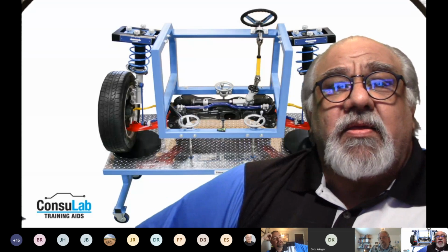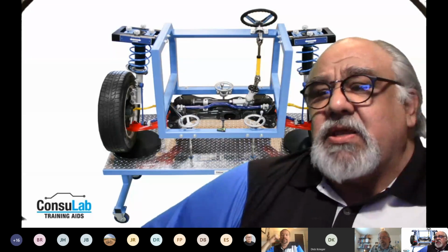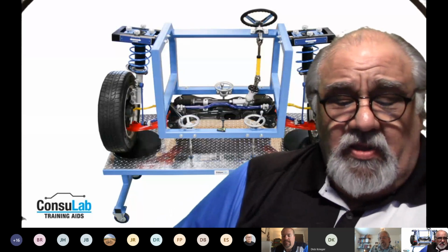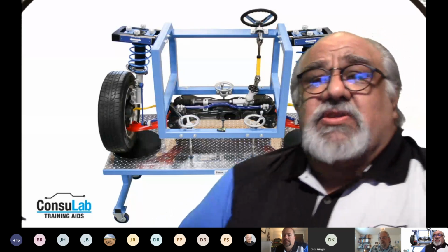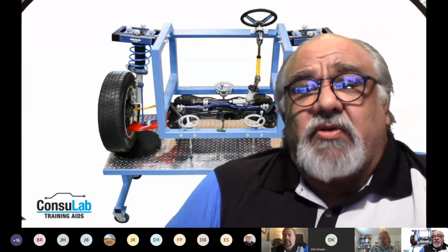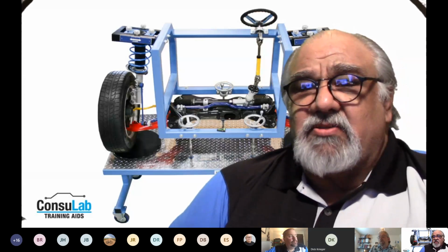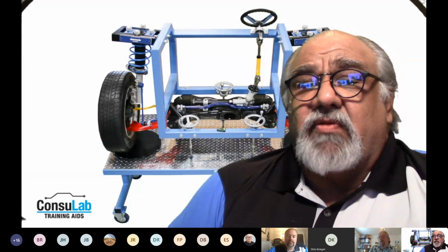Somebody said manufacturers are recommending you adjust ADAS systems after alignments. Is that correct? I would see that as being something you must do. Another big thing that's happening now is you've got steering angle sensors that are all inputs to these devices as well. So once you've done your wheel alignment, some cars have a process where you have to recenter or recalibrate your steering angle sensor as well. So that's another piece. There are some aligners now that plug right into the DLC, so you can do that. It's part of the alignment process.